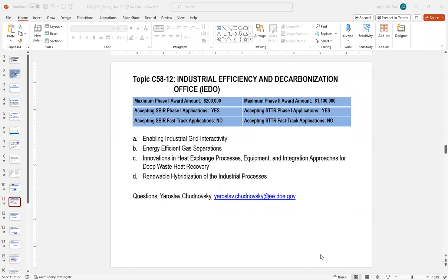But in the past decade or so, there have been some significant advances in the ability to make atomically precise pores, that is, pores that are essentially molecules, and you can make these identical to each other. So if you have an array of atomically precise pores where they're all exactly the same size, then you can make your membrane very, very thin with almost no resistance to flow, and do high precision separations based on size or other characteristics of those membranes.